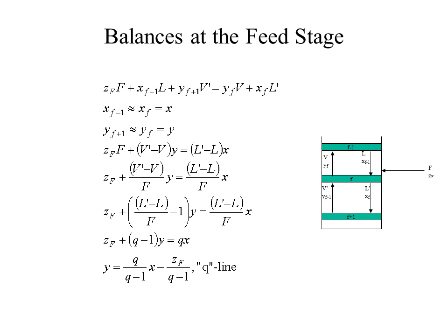Similar to the enthalpy assumption, we'll say that the composition between stages does not change appreciably. Therefore, X sub F minus 1 is approximately equal to X sub F, and we'll call that X. And Y sub F plus 1 is approximately equal to Y sub F, and we'll call that Y.